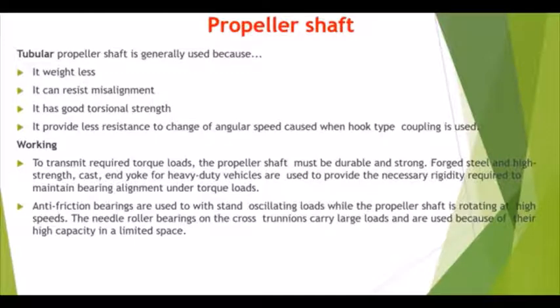The shaft should be straight enough and well balanced with the help of the universal joints in order to avoid any vibration shocks provided by the vehicle. Whatever damage is caused, if the shaft is unbalanced or bent, it will usually wear out the universal joint attached to the propeller shaft.